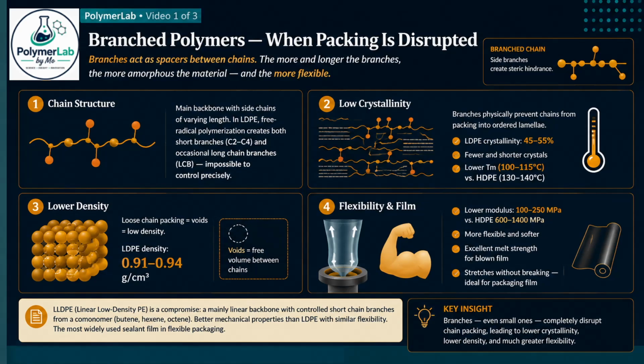Loose chain packing creates voids, empty space between chains that is not occupied by anything. LDPE density is 0.91 to 0.94 grams per cubic centimeter. That lower density is directly visible in the feel of the material. It is lighter and softer. But LDPE excels in applications where flexibility is the priority.